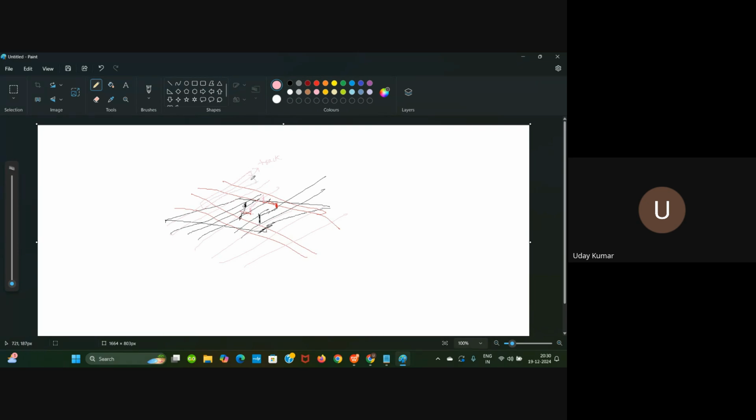Okay. So we will be having a limited amount of tracks and the metal will be routed. The metal will exist where the track exists. So if we use all the tracks, we need to be very, very careful. This is called congestion. We'll discuss. So we need to be very, very resourceful while doing the design. If we use all the tracks and if there are any other standard cells that need to be routed, we cannot route them because there is no availability of tracks. So then the design will come into shorts.